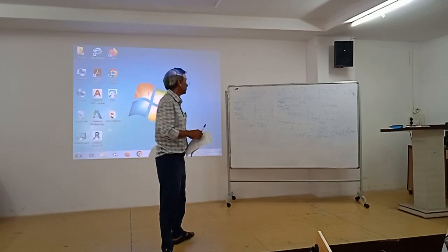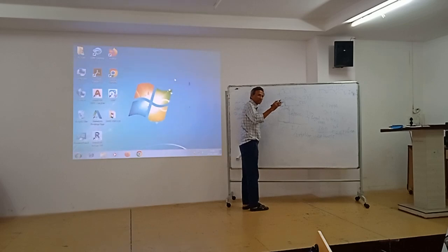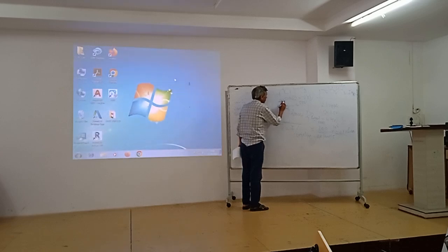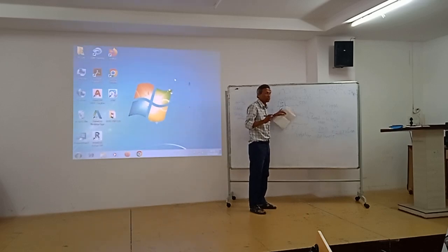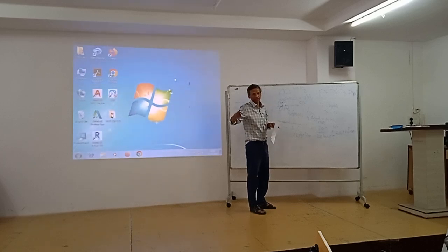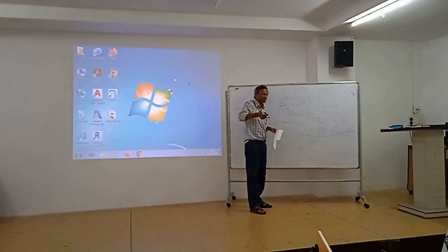Okay, another way of doing this is something called PTC, positive temperature coefficient resistor. You put a PTC resistor in series, so initially its resistance is high. Sorry, that is an NTC resistor. Initially the resistance is high, a variable resistor, the capacitor will charge and then it will reduce dramatically as it heats up.